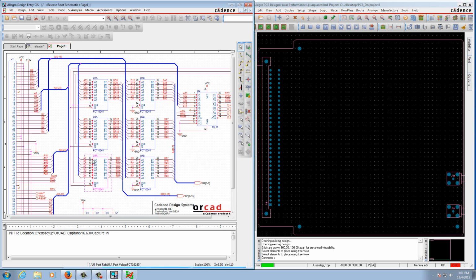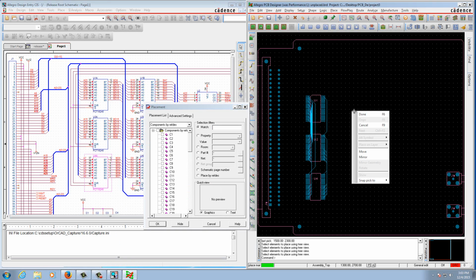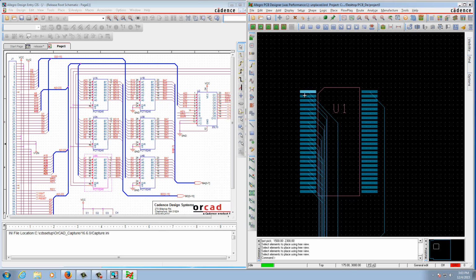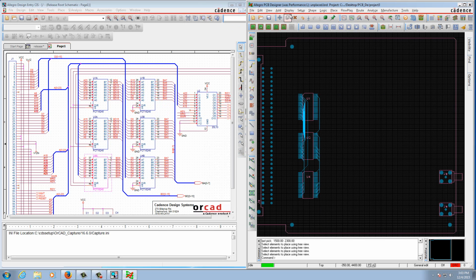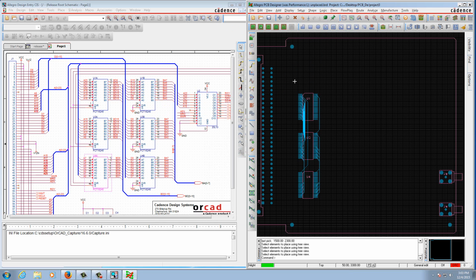Move the cursor over to the OrCAD Capture CIS page 1 schematic window and select one of the FCT components. And in the OrCAD Capture CIS, after you have selected a component, click the RMB. In the pop-up menu, click on PCB Editor Select. Practice cross-selecting components in OrCAD Capture CIS and moving them in the editor. When you are finished, click Done.